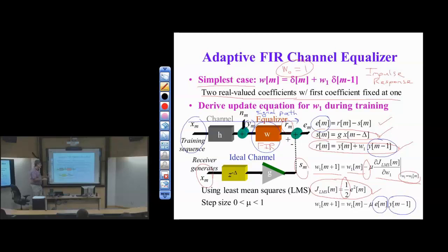And again, there's nothing in here that talks about modulation type or method. There's nothing communication system here. It's just a training sequence, which is PN or whatever, and an unknown channel or unknown media between transmitter and receiver. It's not for anything in particular: audio, biomedical. We use this in image processing, video processing. It's a very generic method for equalization, with the goal of having the cascade of the channel and the equalizer being close to all pass. That's the goal. The equalizer is supposed to undo the frequency distortion in the channel.